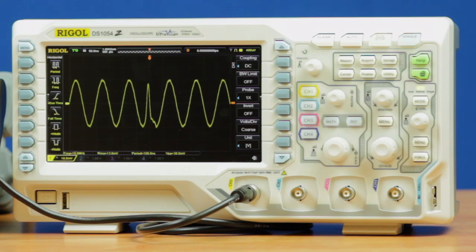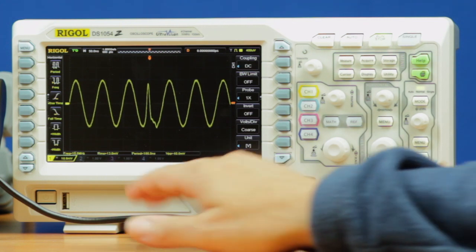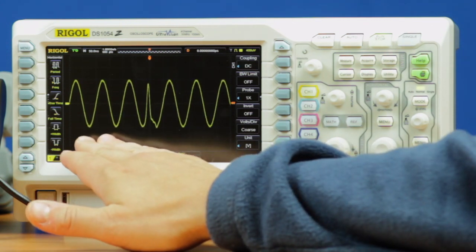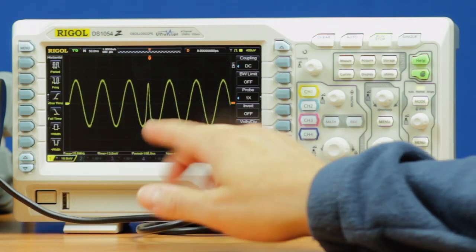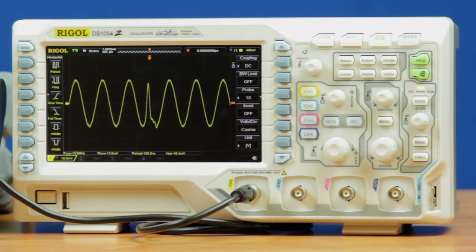And here on the scope we can see we're now triggering on the change in that phase using a pulse trigger mode. And now you can see that on the left side of the screen the sine phase is normal, but then right as it switches in the center you can see it's offset by 1 division of where it otherwise would be. So it's inverted, or 180 degrees out of phase. So that is a single transition going back and forth of 180 degrees in phase.